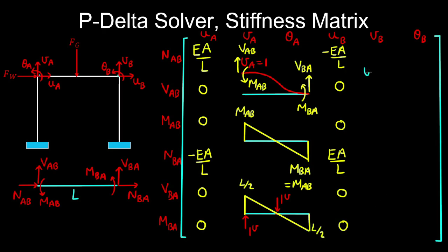So therefore the displacement at A is the volume enclosed between the real and virtual bending moment diagram. So we have MAB multiplied by L on 2 multiplied by L on 2 on 3 EI. That gives the volume between these two triangles, and we'll just multiply by 2.